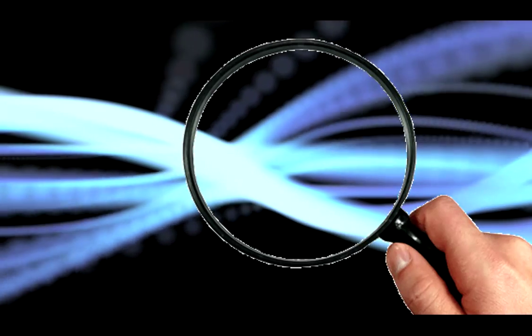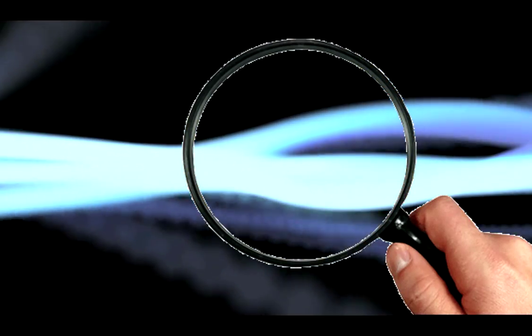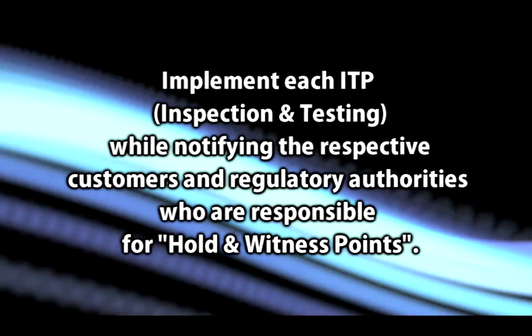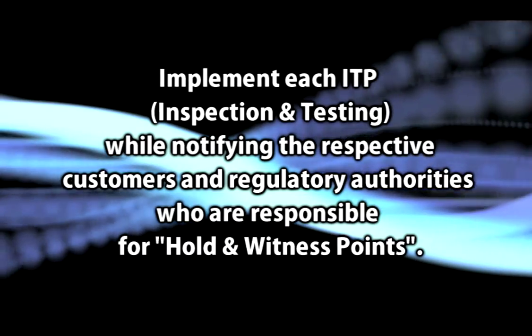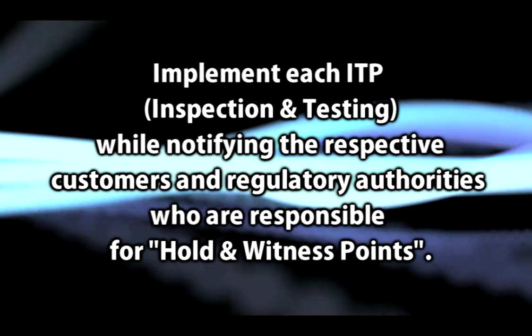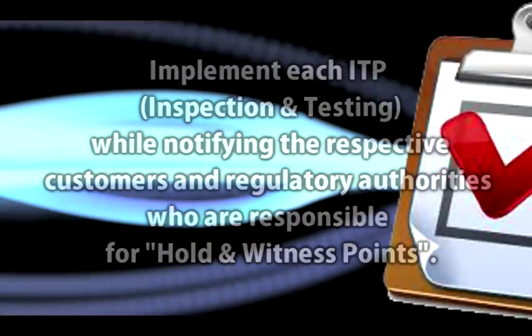A clear procedure has to be put in place for prior notification of hold and witness points to the right person. Finally, implement each ITP or inspection and testing plan while notifying the respective customers and regulatory authorities who are responsible for the hold and witness points. Maintain proper recording of ITP results on checklists which are approved by the responsible persons.